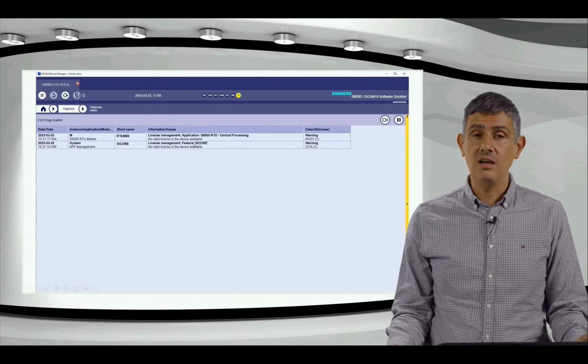We have also some working area here, and we have additional tabs for single line elements and for signals. The first step would be to create a new graphic. So we click here, we give it a name, like for example, Bay1 single line diagram, and we select a type, like only single line. And then we confirm.